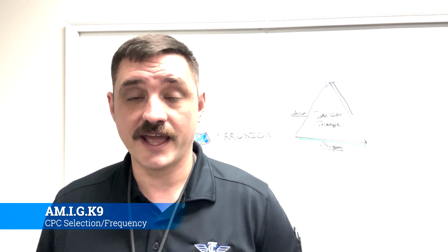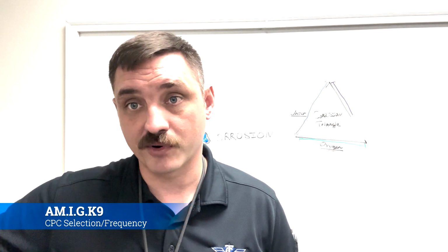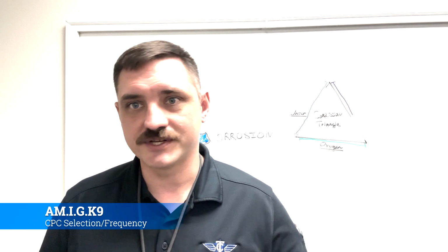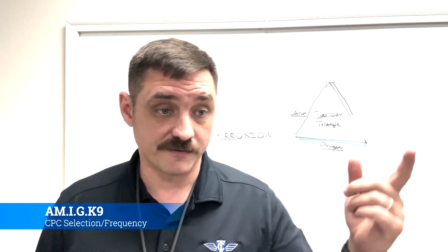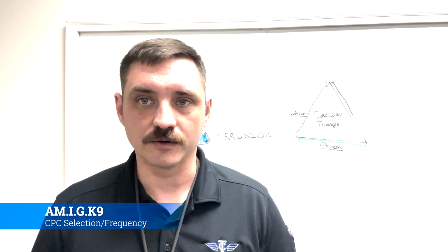It will say, hey, look, every 100 hours do this, apply this lubricant, apply this CPC, whatever. If they don't give you an exact product, it'll give you at least a standard to shop products on. So that's how you know. LPS3 goes to a mil standard, whatever it is, and whenever you see that mil standard, you just know that's LPS3. I actually printed all that out and translated it into product names, so I don't have to do that thinking anymore whenever my 100-hour rolls around.